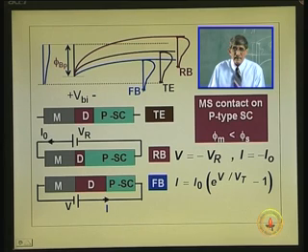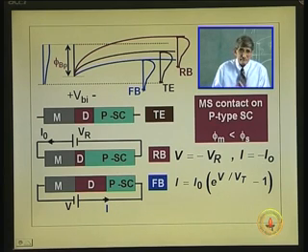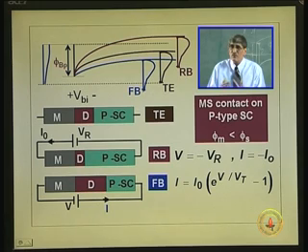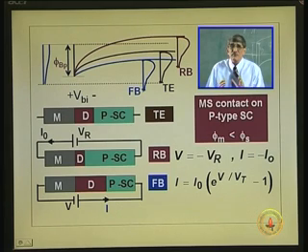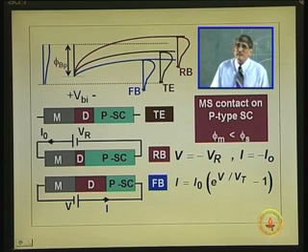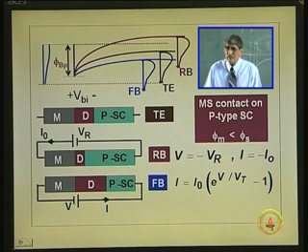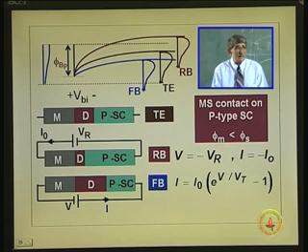So, the current transport is there in the forward bias case. In the n type semiconductor, the current transport is transport of electrons from semiconductor to the metal. In the case of p type material, forward bias barrier is reduced, current transport is due to the transport of holes from the p type to the metal. So, current directions are different. In the case of metal n type semiconductor, in the forward bias case current is from metal to semiconductor, just like p n junction, p to n. In the case of p type semiconductor, current is from p to metal, that is like a p n junction. Okay. These are the things to remember.